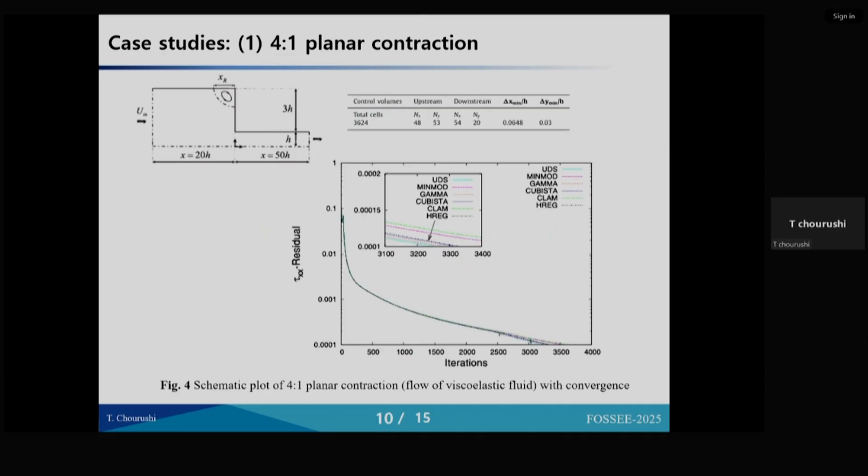Now, the real test case problem. In this case, I tried to study real fluid cases. This test case represents a 4:1 contraction channel, wherein the outlet is one size and the inlet channel width is 4 times that. The fluid allowed to enter here is a viscoelastic fluid. Such conditions do occur in industry, because many of the industrial oils and waxes we use represent the characteristics of a viscoelastic fluid. This fluid offers a very good test to the numerical scheme.